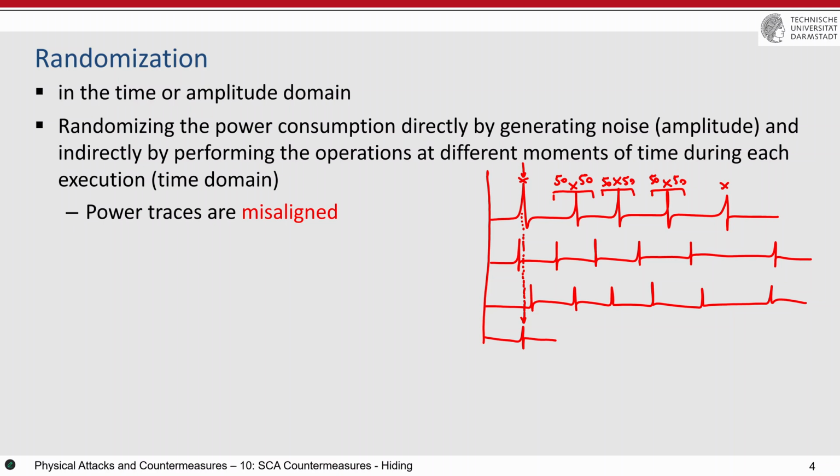And then extract another trace, which means that you turn this into another trace which has just 100 points, and then 100 points, and then 100 points. You do this for every trace individually, so that you make another trace which is well aligned. And this one is also well aligned based on the peaks, on the clock cycles. And so on, and then you perform the attack on these traces, not on the misaligned traces. Then you need some pre-processing steps.